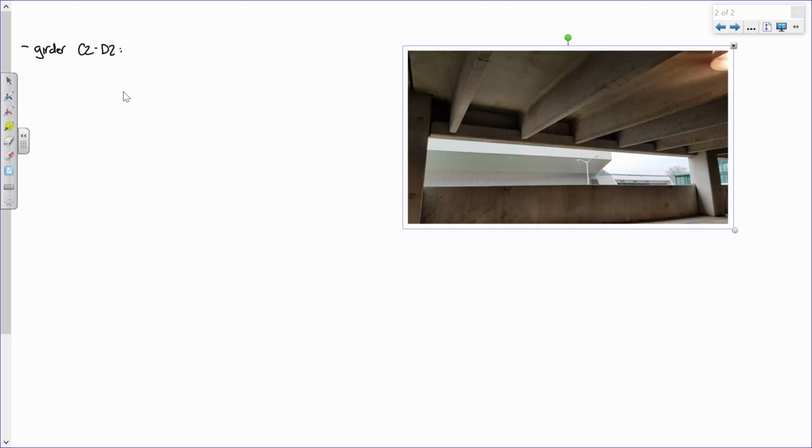Let me ask you a question. That floor beam we just did, what were the reactions again? 3,000 pounds? Okay, so you're telling me I have a floor beam in the building and the ends are seeing 3,000 pounds. Where does that 3,000 pounds go? Columns. Columns, that's one place it goes. Where's another place it goes? Connecting girder. Connecting girders, right?